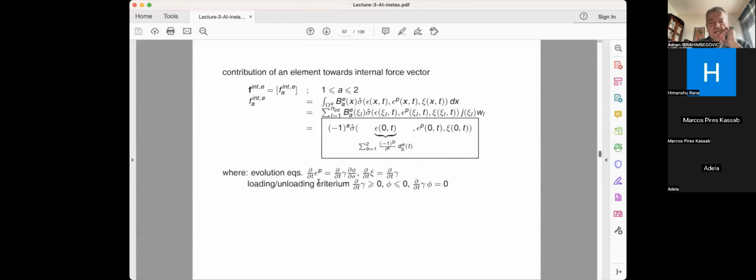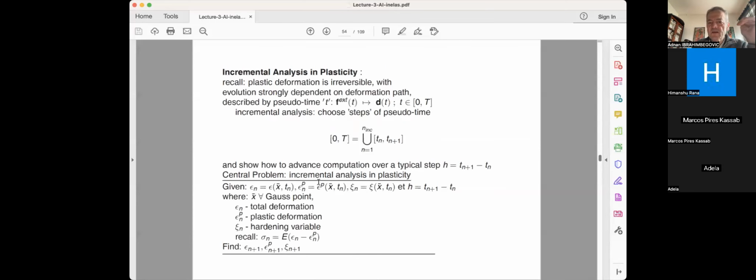So typical story is we now use a time integration scheme with one step, because one step really simplifies the storage for the internal variable. If you had a multi-step solution method, that would be really a nightmare, because you would have to do bookkeeping, taking plastic strain from I don't know how many steps. So really the one-step method is for the simplicity of handling the database management for this type of case.